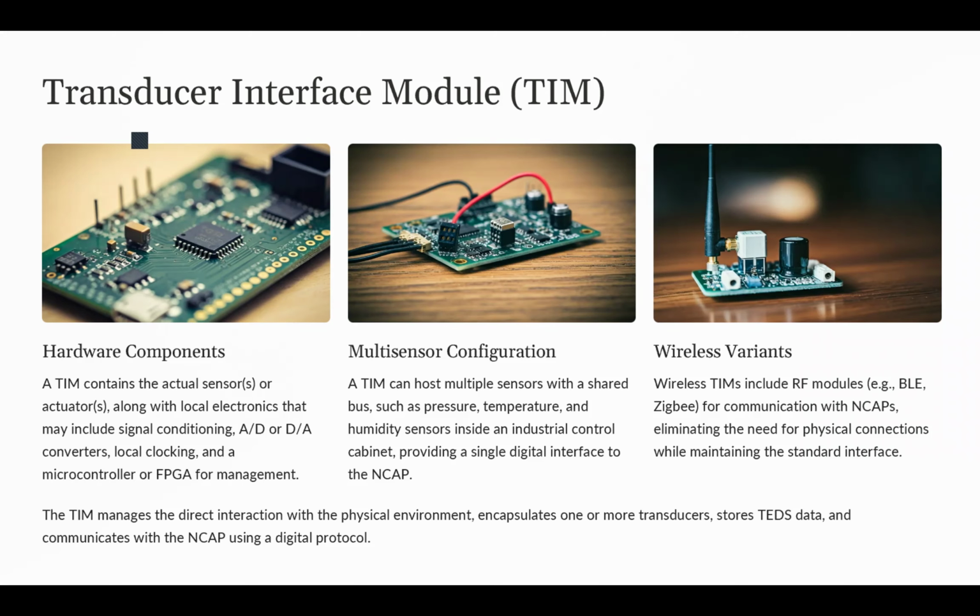Now, before we convert the data to digital, the raw data, which is an analog signal from the transducer, is processed using some amplifier or filtering, or if we need it, a linearization circuit. Basically, all this happens so we can make sure that we have an accurate and noise-free measurement. So it's pre-processing to enhance our measurement regarding accuracy and noise.